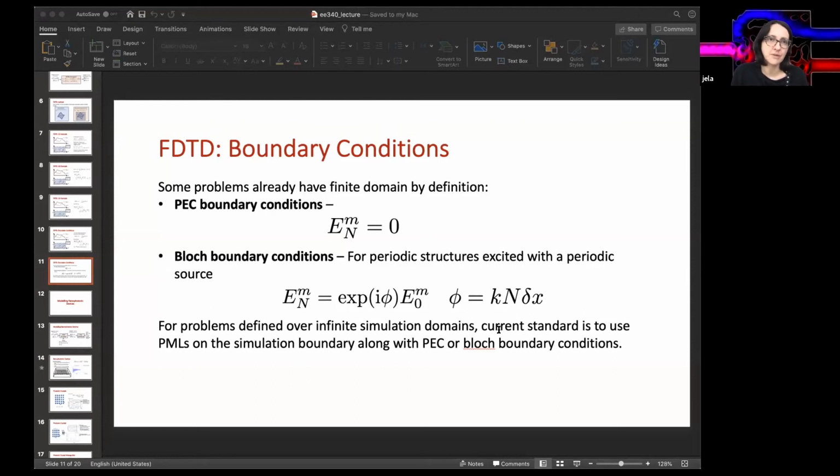So if you want very fine resolution in frequency, if you're simulating a high Q resonator, or capturing something that has a very small line width, or some sharp changes in the line width, then your simulation needs to be very long, because the frequency resolution is inversely proportional to the duration in time. And of course, there are other conditions for convergence, which relate the stepping in time to the stepping in space.